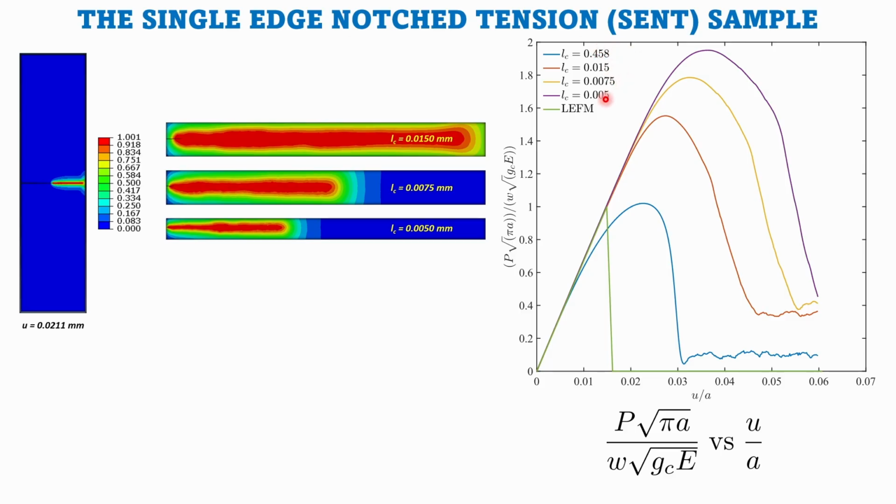So what you can do is, if you are designing a particular material with respect to failure using phase field modeling, you can apply the toughness scaling that I talked about. You can do a phase field simulation using the actual LC or the predicted LC from the parameter identification and see if the peaks match with LEFM.